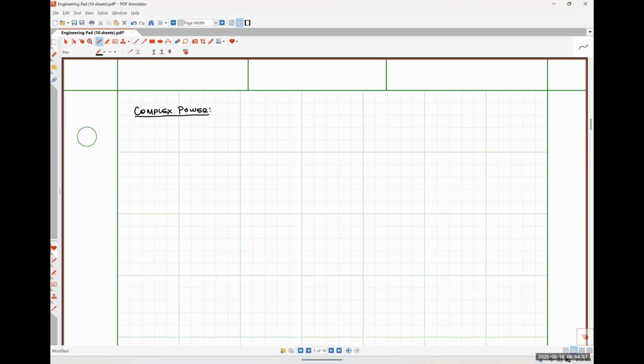So all of our complex power calculations are going to be done using RMS phasors. So I want to make sure that you guys can accurately find your RMS phasors when you're given any information, okay? So I'm going to start with a time domain voltage, okay? So Vm cosine omega t plus theta v, okay? Now, the exact same process can be used for currents. I'm not going to bother writing it down because it's literally the exact same thing, okay? So just know that it can be used for currents as well. So we've already talked about this guy right here. This is a time domain signal.